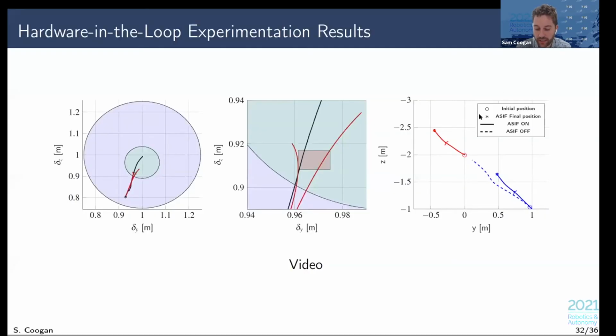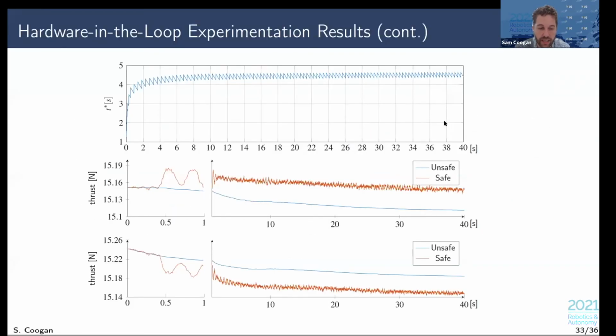So what I really want to highlight about this example are in the next few slides. So let me just show some plots, what's happening here. So in these bottom 2 plots, we're showing the thrusts for the 2 multi-rotors. Excuse me, I don't label which vehicles, but this top plot is for the first quadrotor, the upper one, and the bottom plot is for the lower quadrotor. The blue trajectory shows the desired thrust. The orange trajectory shows our filtered thrust, which keeps us safe.